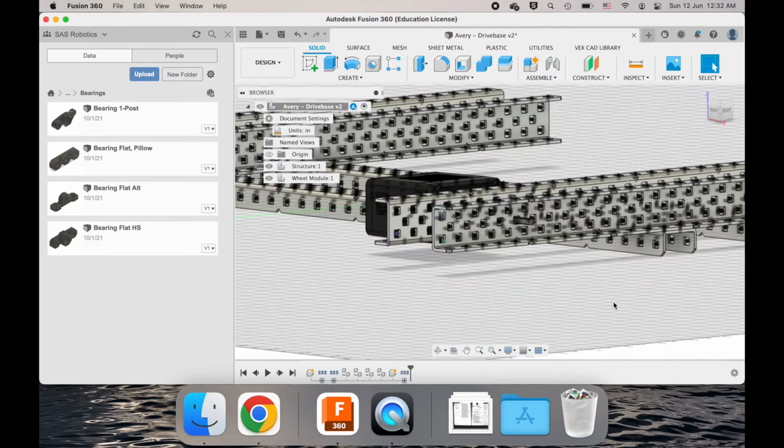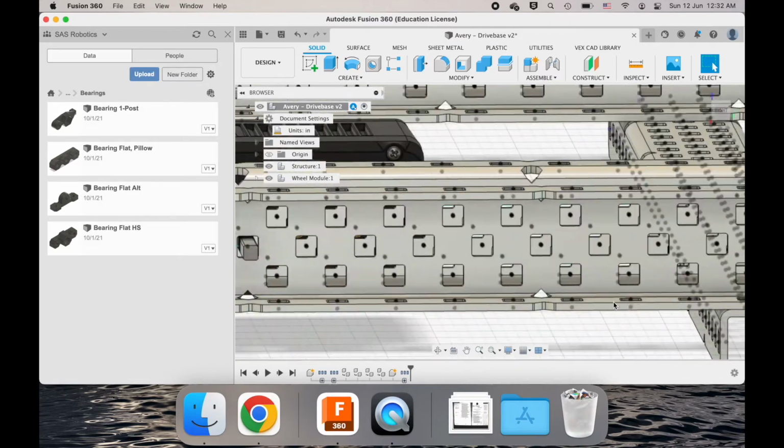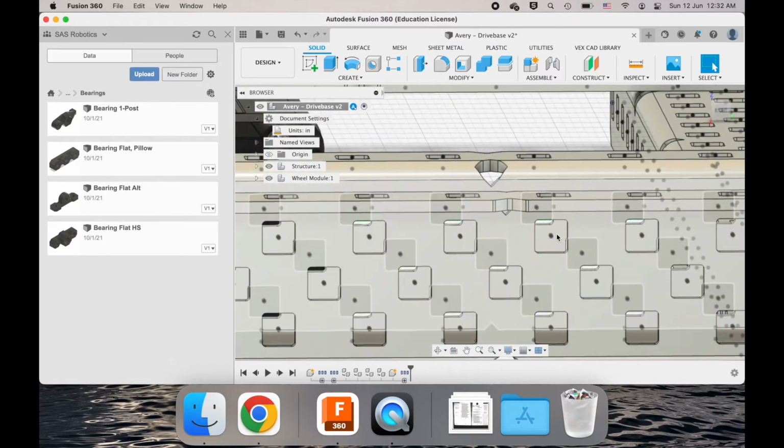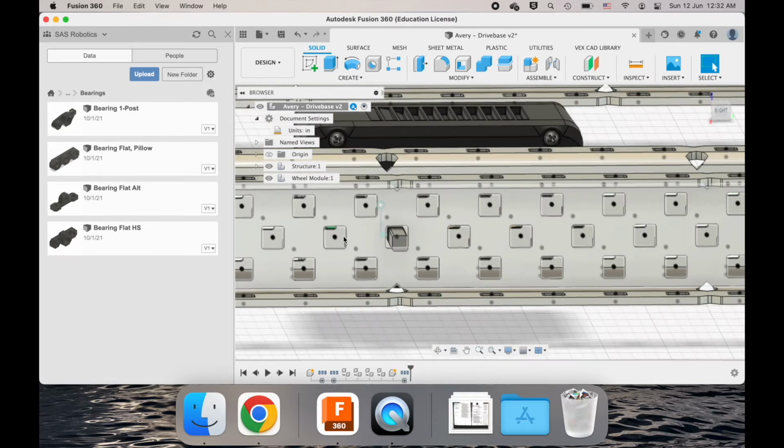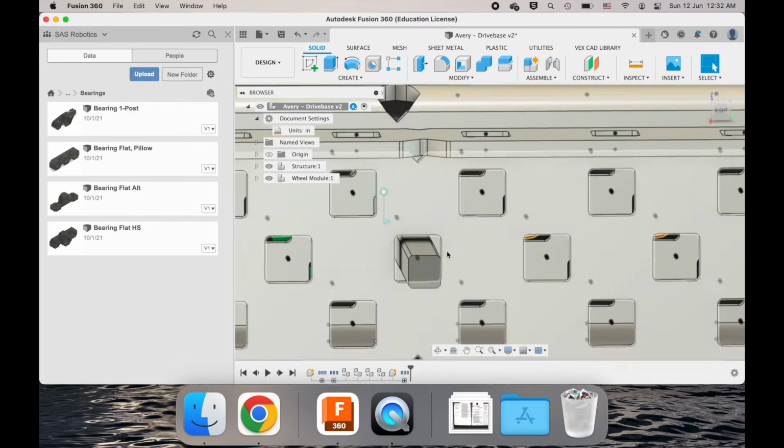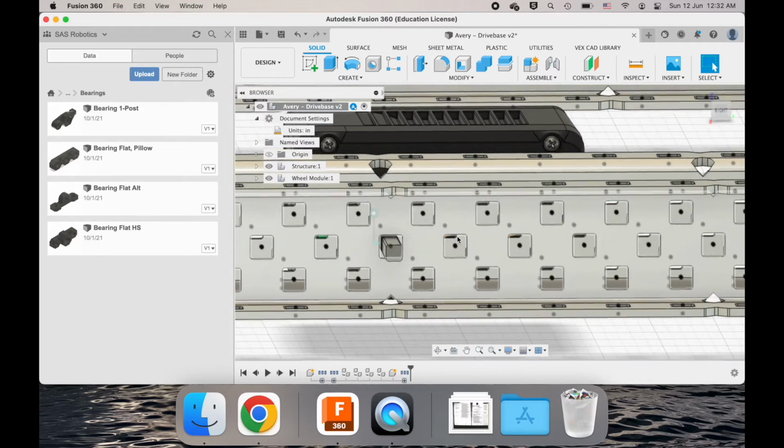All right, let's look at these holes in the C channel. Okay, they're very squarish, right? And now we actually have an example of an axle here, which is also very squarish. Okay, and if you try to turn a square in a square, that is not going to allow you to turn smoothly within the hole, right? So we put in these pieces called bearing flats.